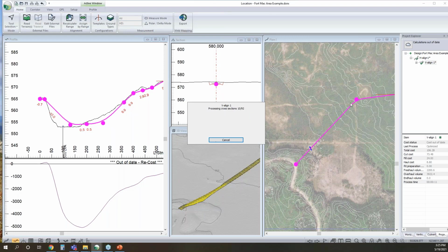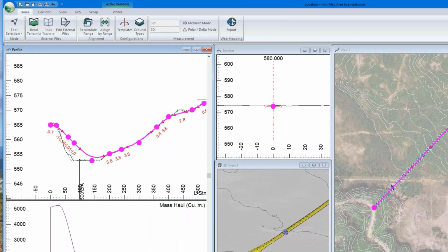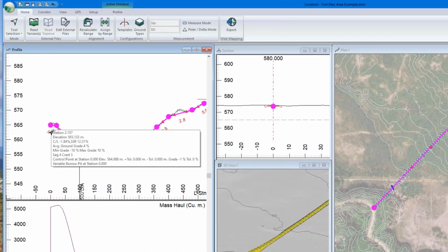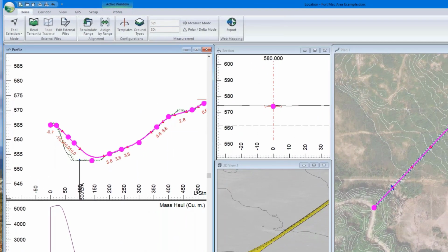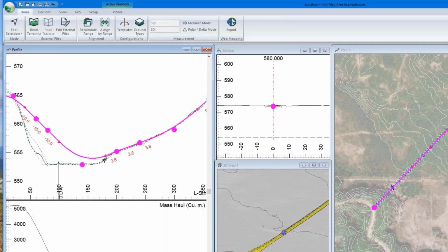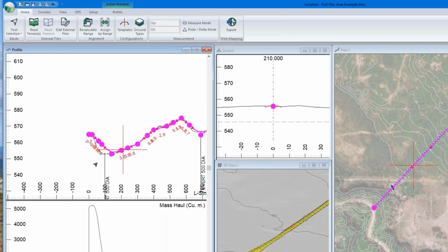So it's going to cost a little bit more than that previous example that we have, but it's going to be buildable in there. And that makes sense too. We're generating our material at the start of our road from a pit. So we've dealt with the deficit, and then afterwards it makes sense to follow the ground as closely as possible to minimize the earthworks.